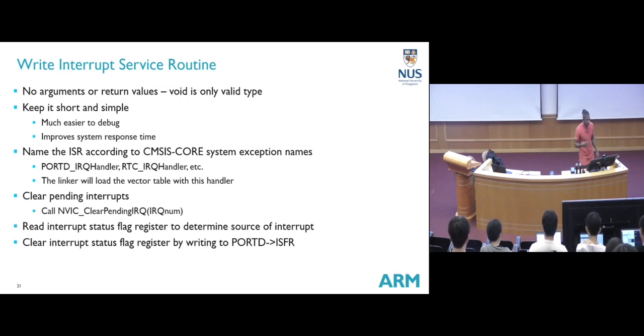So some other stuff about ISR before we go in that direction. Interrupt service routine, again some important things you must know. There are no arguments and no returns. There's no way you can pass an argument to an ISR and there's no way you can get a return value. Of course, one of the ways you can do it is what you like to do always, right? Global variable. I'm sure your code has 2000 global variables by the time you finish. But of course it is not a good practice. Don't put everything as global and say it solves all my problems. No need to send, no need to receive.